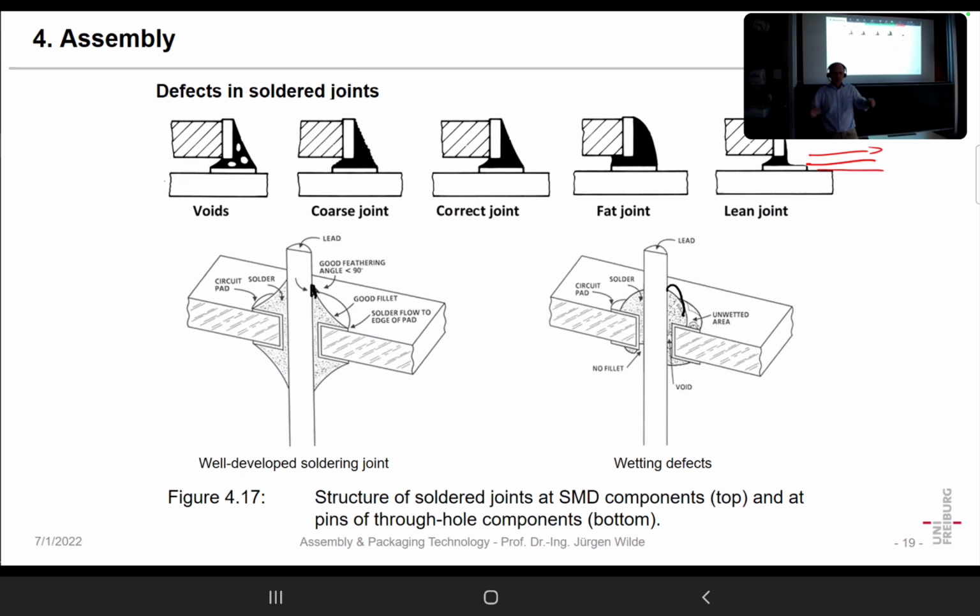And so you accumulate iron and aluminum and magnesium and sodium and copper and what else? And nickel. And this gives a higher content. And at some point of time, you can see these impurities because then the solder joint is no longer shiny, but it looks a little dull, you could say.